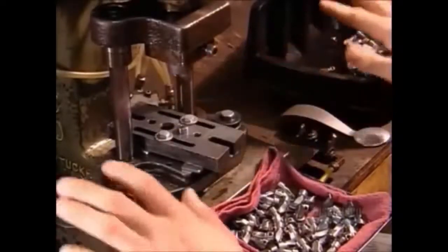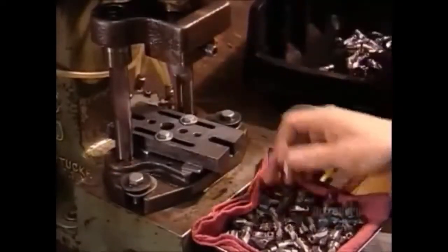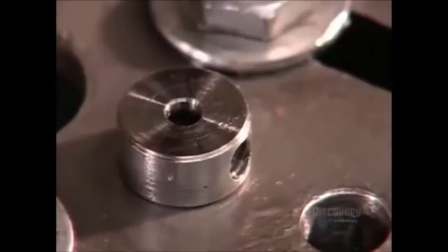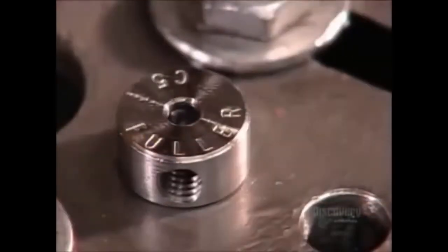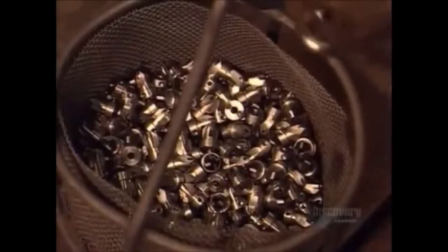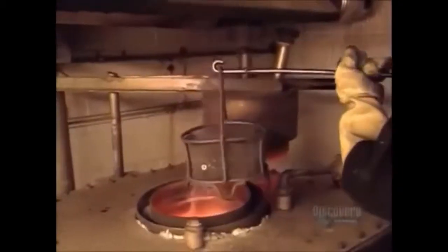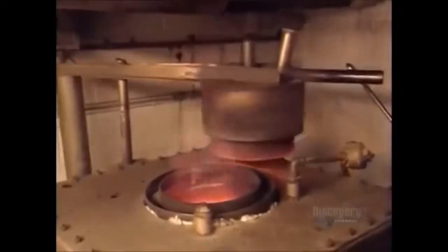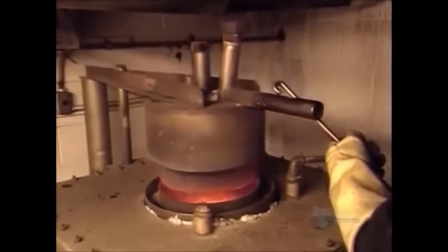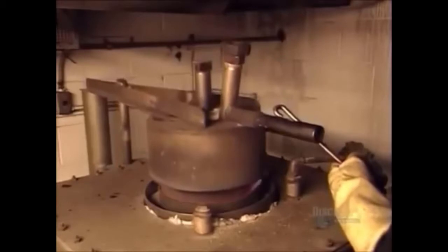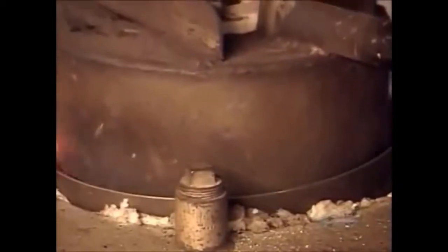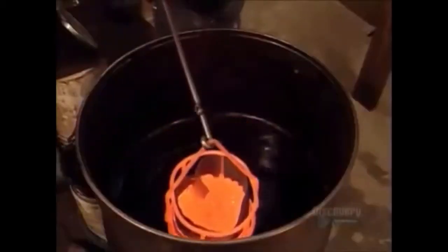Back to the countersinks now. The steel is still relatively malleable, so a worker runs each one through a stamping machine that imprints the size of the tool and the company name. Whereas the drills are made of a different type of steel that's already hard enough, the countersinks and plug cutters must undergo a heat treating process to harden, about 20 minutes in a fiery oven, along with a secret recipe of chemicals. The intense heat, 955 degrees Celsius, transforms those chemicals into gases which then permeate and harden the steel.